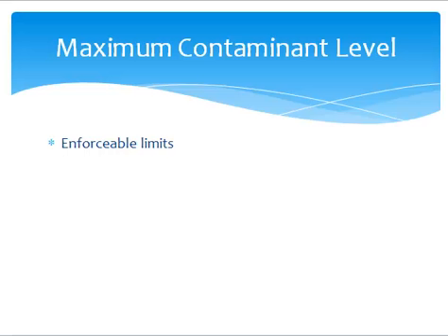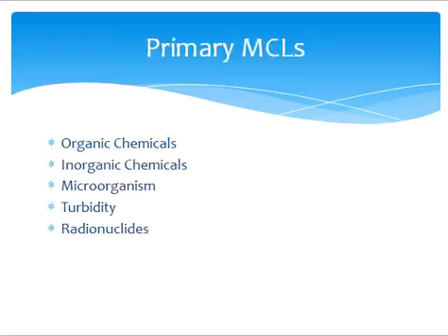Maximum contaminant levels are the enforceable limits of a contaminant in the water. These are divided into primary and secondary MCLs. Within the primary MCL category, we have 5 subdivisions. Primary MCLs assume approximately 2 quarts of water consumption per day for a lifetime. This would give a 1 in a million chance of developing the related health effect. Generally speaking, MCLs that are exceeded do not pose an immediate threat, but instead cause harm over time.